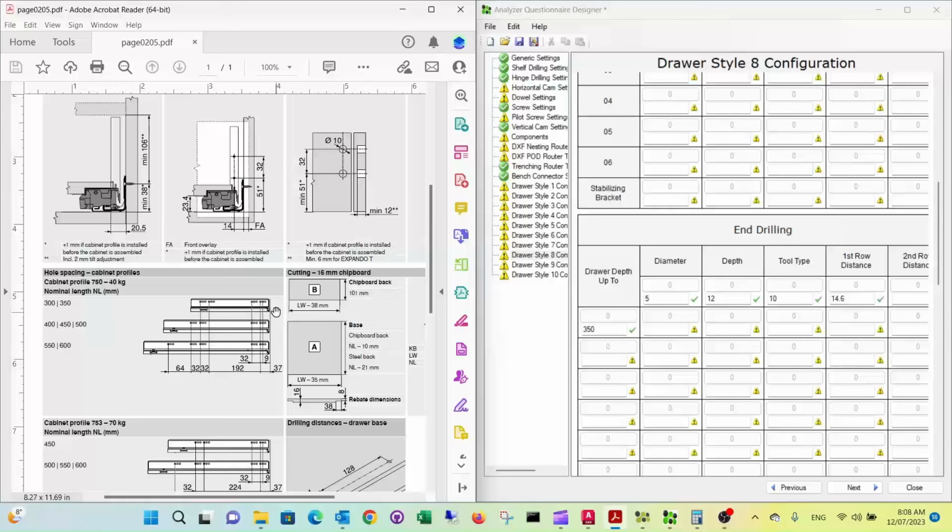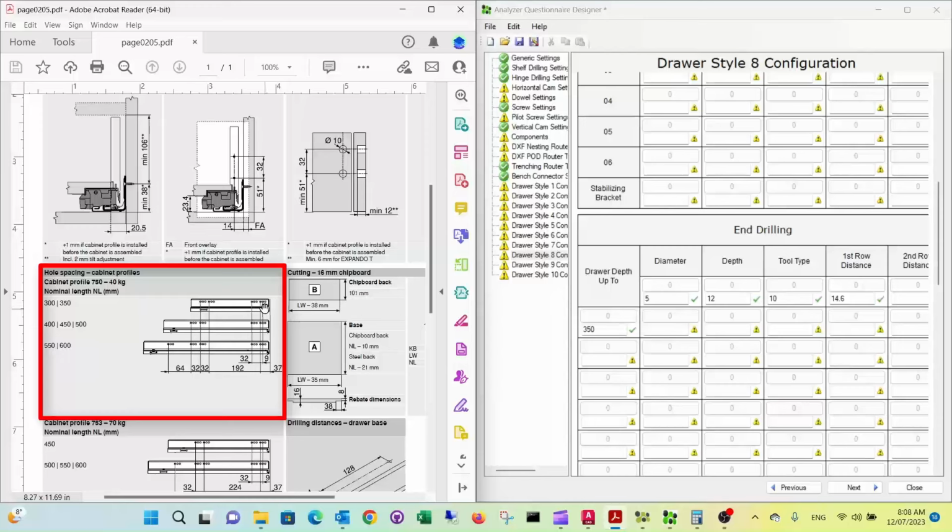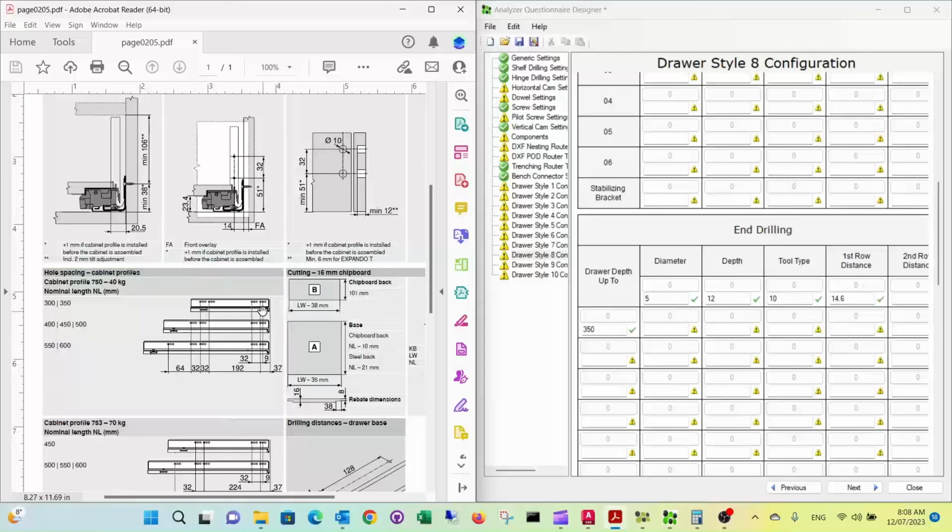As for my drawer runners, I prefer to have a fixing at the very front edge of the cabinet. So I want to use the hole, that's the very first one here. So that's 37 mil minus 2 times 9. So that will end up at 19 millimeter from the front edge. And the next one, I'm going to use my 37 mil hole there.